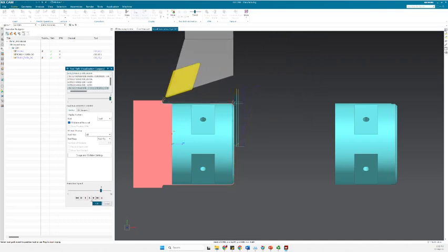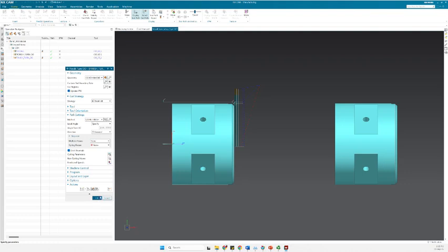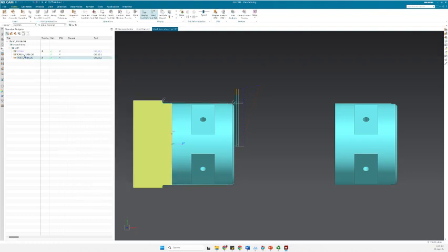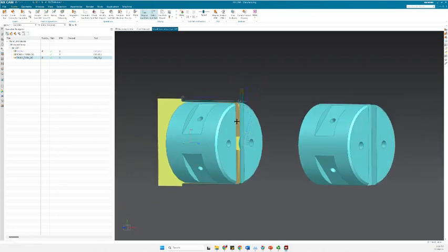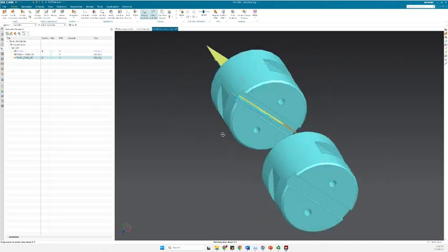Now we have reached the final geometry. So for now, we have defined facing, rough, and finishing on the outside diameter. Until now it was rather similar to the turning, except that the geometry was defined differently. Next is defining the milling of the end slot, one of them on the surface and 3 of them on the outside diameter.